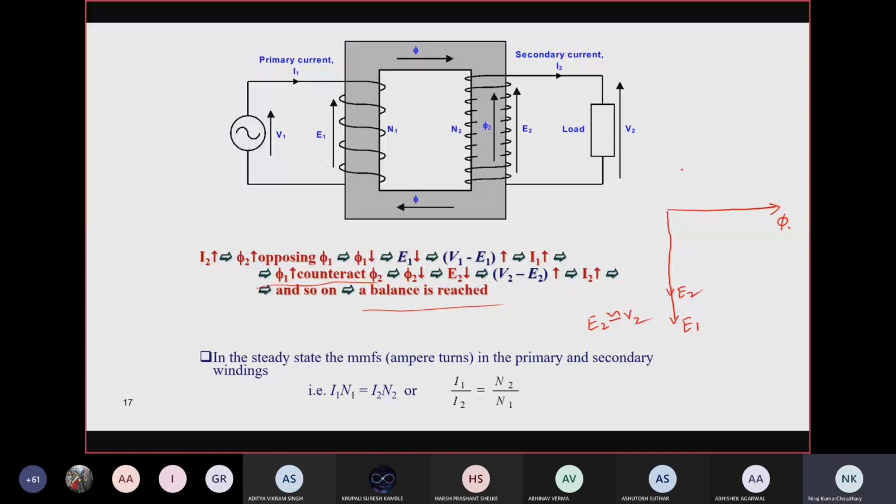E2 will be equal to V2, ठीक है? So here V1 होगा इधर फिर से, ठीक। Now we have a secondary current I2. I2 will lag E2 or V2 by some angle, phase angle, because mainly the coil is inductive in nature. So suppose this is I2, ये एंगल मान लो कि है phi 2, एंगल बिटवीन V2 एंड I2 is phi 2, ठीक है?